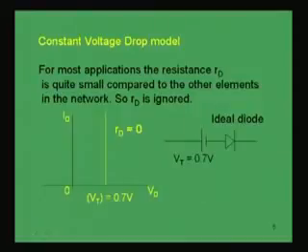So, in the characteristic, if we now see, there will be this 0.7 volt for silicon, which is the threshold or cut-in voltage, and the characteristic curve will be rising vertically because this resistance is 0, it will be rising to infinitely high current. This is the representation we get after simplifying the piecewise linear model with the assumption that RD is 0, which can be ignored or neglected.